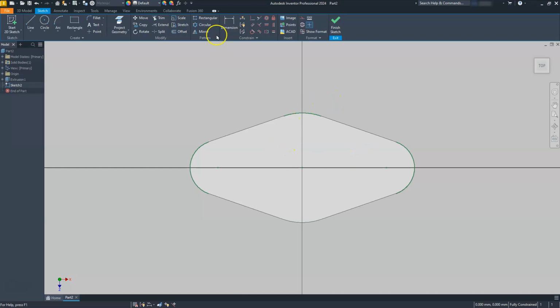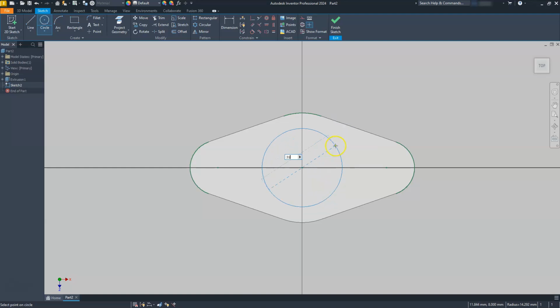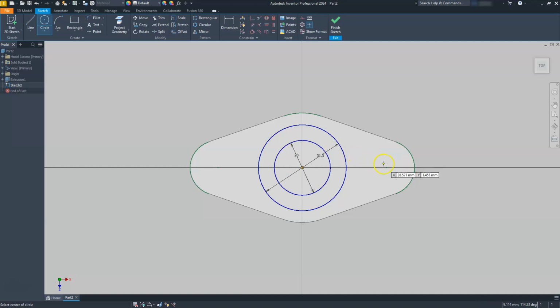And then I'll go ahead and put those circles on the inside, right? These are going to be diameter circles. So I'll select this circle, go to this center, kind of give me a preview, do the right click, choose diameter, and then type in 31.3. Go back. So it's still asking me to create my next circle. I'll click here, giving it a diameter. This is 20. Go to this side, click on that center, kind of preview it. This one has a diameter of 15. And then the one on the inside of this one has a diameter of 10.